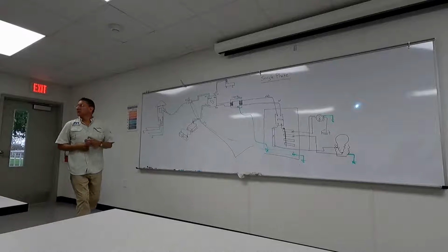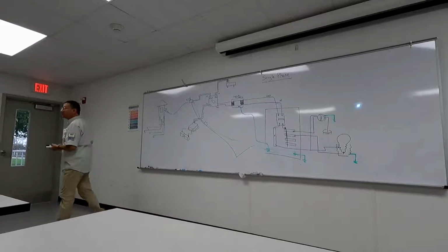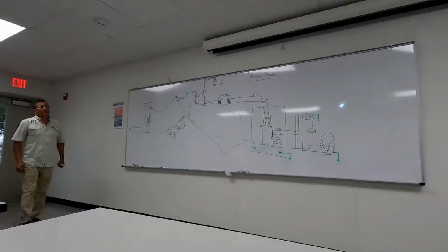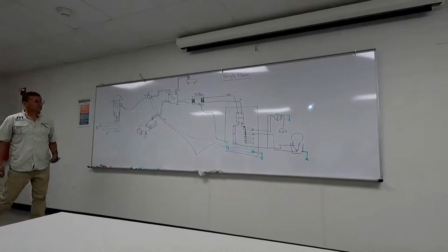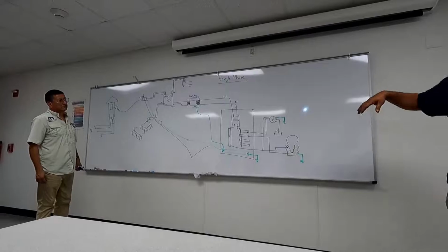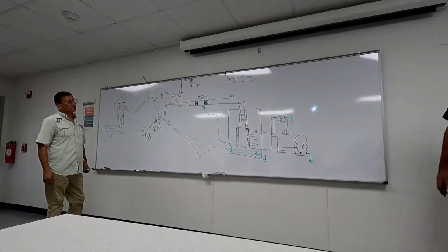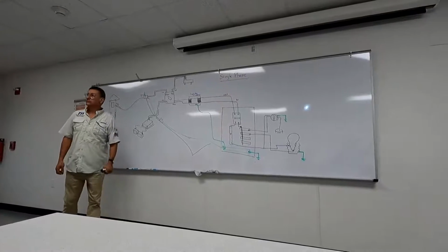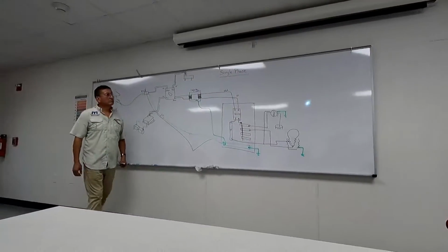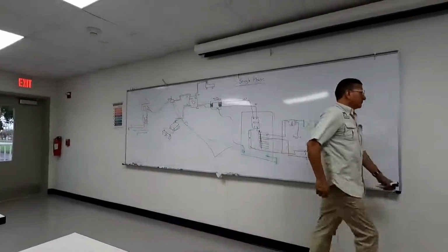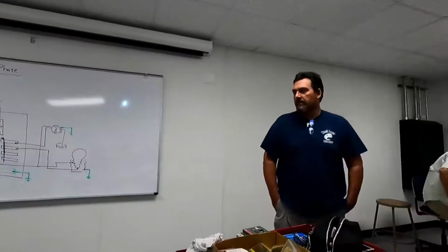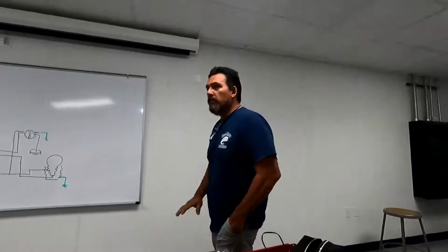Okay, guys. So, for the ground from the battery, you said it will connect to the AC? It will eventually, but not directly. The bonding system is tied into the negative, but it's separate. It's nothing that you want going directly to the battery. Is there an element that restricts the flow from the grounding bus bar to go back? No, it's just natural. You just don't want it, because if it's a major problem, it'll take the battery out and lose everything.